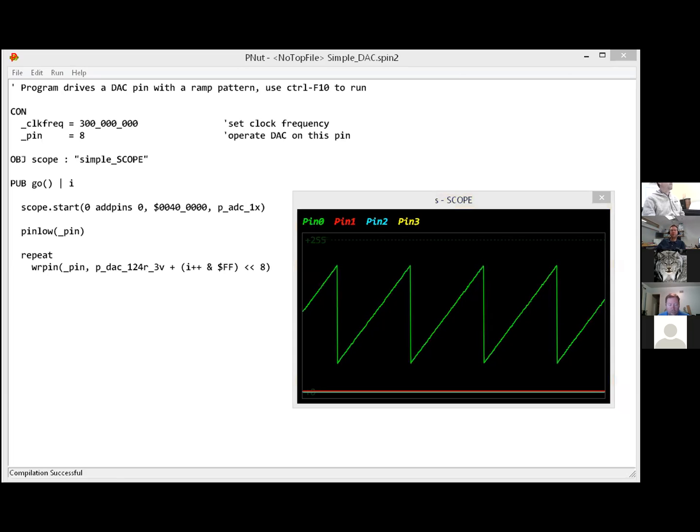And Chip, what's the ramp frequency? Oh, okay. So yeah, everything is kind of virtualized here. We're sampling it at kind of a low rate here, I think about 200 microseconds. So in 200 microseconds, it's doing 256 of these steps. So it's about 1 microsecond per repeat loop. And that's really driven by the fact you're graphing it, right? Because you don't have any pauses in here. Yeah, I don't have any timing graticules on this scope display. It's 512 samples, and this is all being pulled in from that thing called Simple Scope.